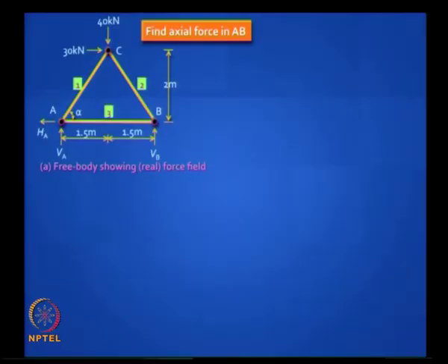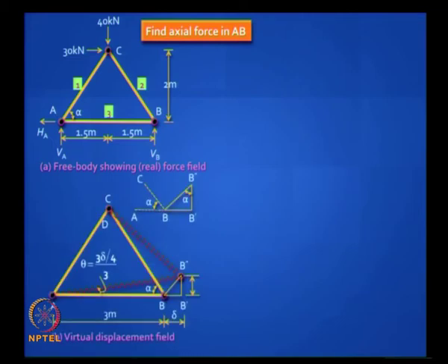You can also do it in a truss. Let us say you want to find the reactions in a truss, this particular example. This is a tricky thing, not the reactions, those are easy to find. I want to find the actual force in AB. What should I do? Well, I should now have an elongation in that member AB. Let it elongate by delta, but then if I keep this B here, I have a problem because I will also be elongating the bar BC.